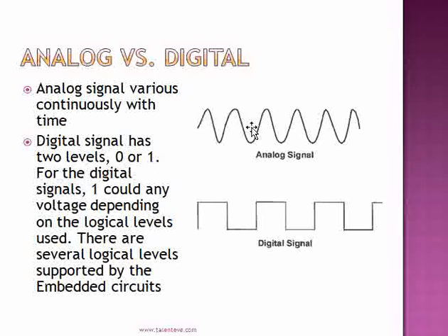We would need to perform some other activity in between, so that both of them understand the common voltages. So logic levels help us bring down that communication gap between the driver and the receiver, and the communication happens without any issues.